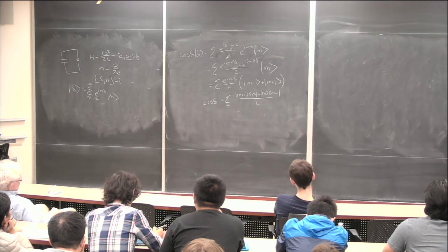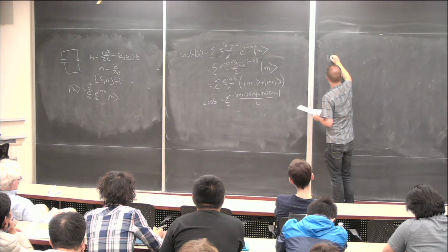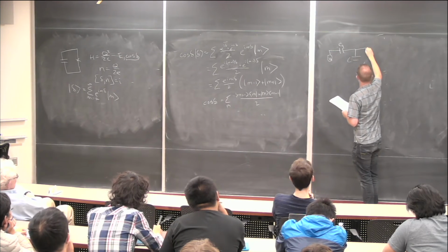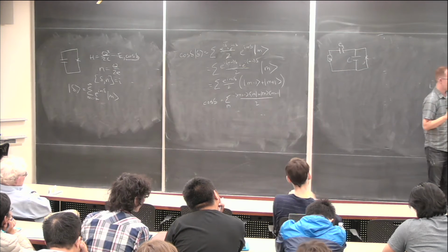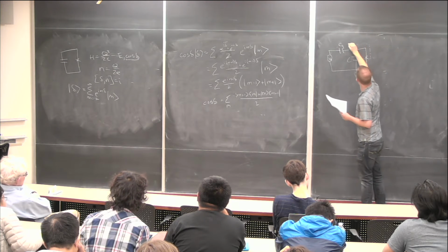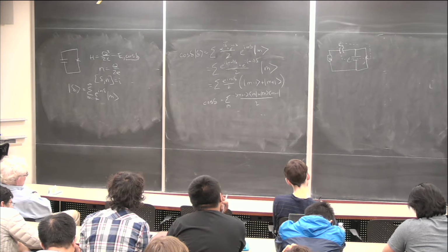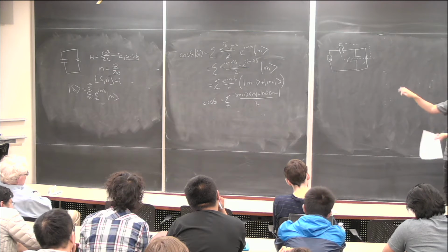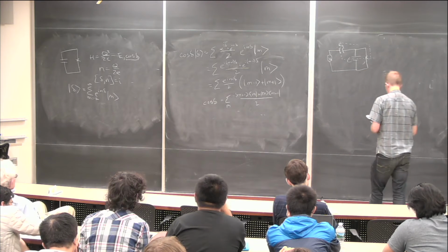And there are reasons that we started out there as a field. So the device looks almost like the one I drew there, but you also have some gate voltage and some gate capacitor, along with a capacitor C and a Josephson junction like that. Okay, so if these capacitors are relatively small, this thing has a small island, which I've put in this dashed box, which is not connected to anything else except through this tunnel junction. And so you can think of some discrete number of excess Cooper pairs on this island or this box, which is what our n variable represents.